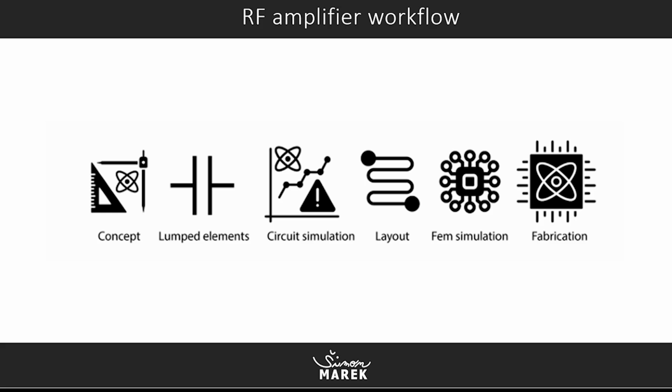So this is our RF amplifier workflow. You start with the concept, you do some lumped elements, you design your circuit, then you do circuit simulation, then you do layout of your RF circuit, and then you do FEM simulation if needed. If not, you can skip this step and go straight to fabrication. Once the RF amplifier is fabricated, you can simply measure it and see its performance.